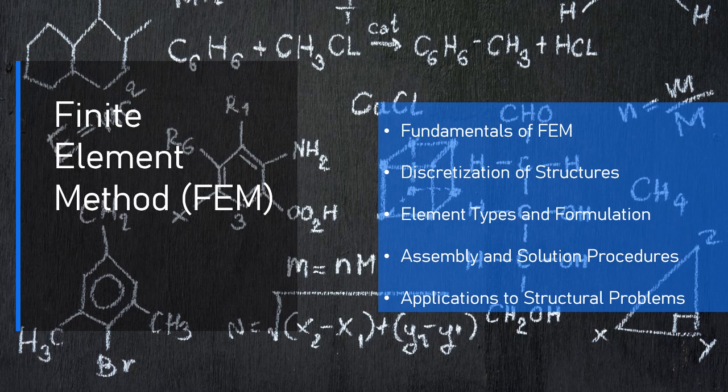Advantages: can handle complex geometries, adaptable to irregular shapes. Disadvantages: more computationally expensive, harder to generate. 3. Hybrid mesh. A hybrid mesh combines structured and unstructured elements. For example, it may use structured elements in regular regions of the domain and unstructured elements in more complex or curved regions.